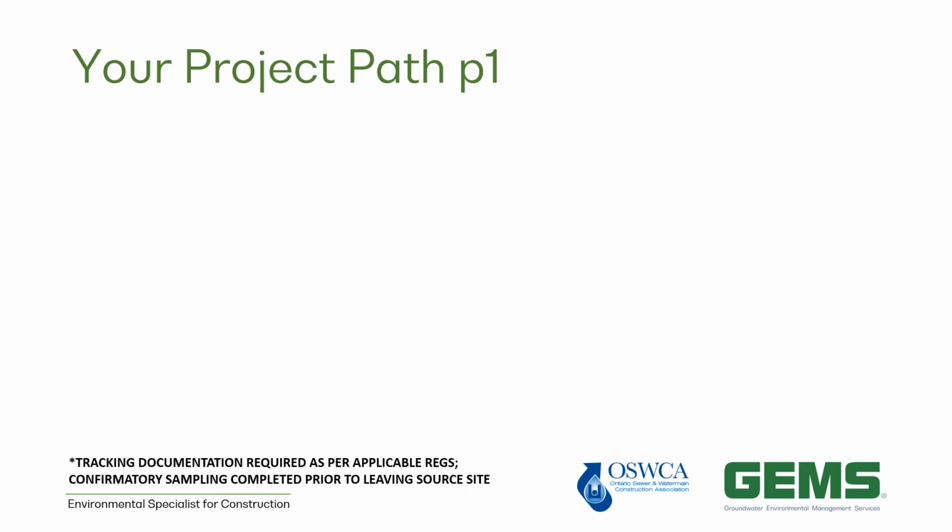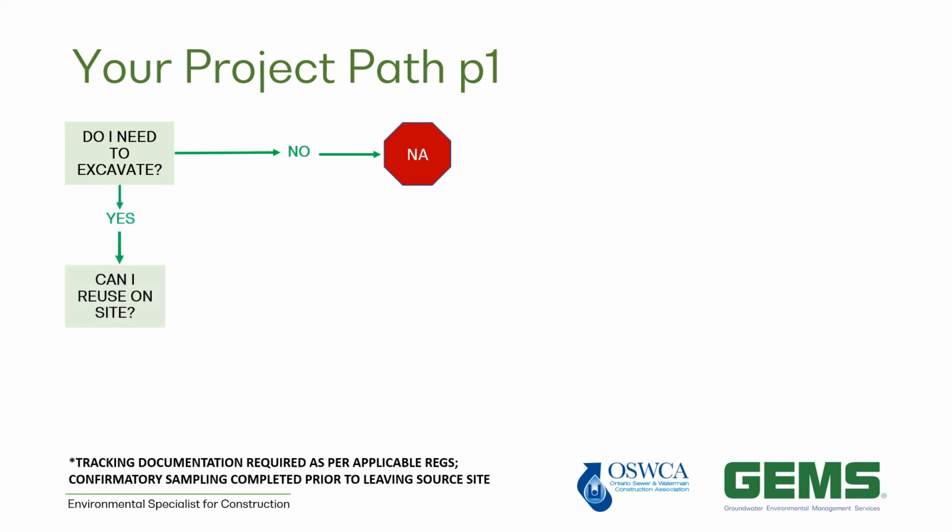So the first question you're going to ask yourself is, do I need to excavate? If you don't need to excavate, then the excess soils regulation is not applicable for your site. If, however, you do need to excavate, and I'm sure most of your projects are going to include excavation, you need to determine if you can reuse that soil on site or not.